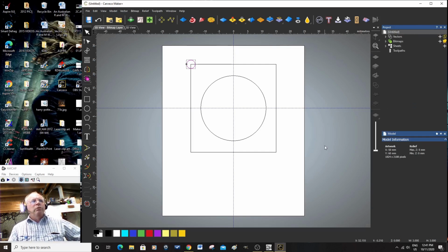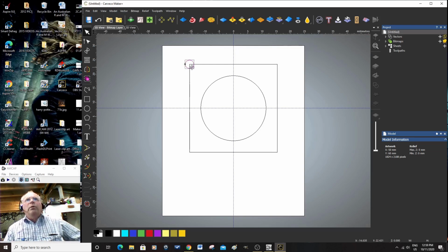Okay, now we can use another tool here in Carveco to accurately place the additional holes here. So what I need to do now is make another 3 very accurate holes or drill-ins on the apex of this square.